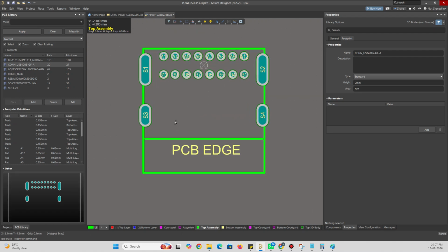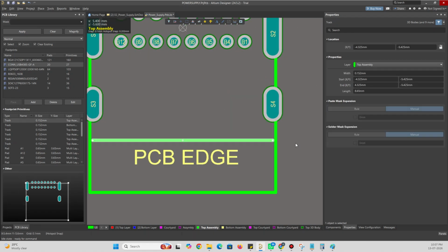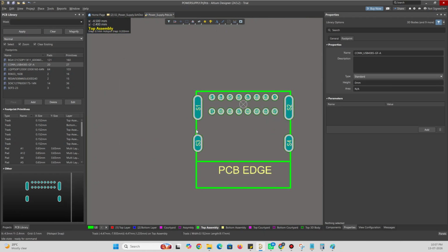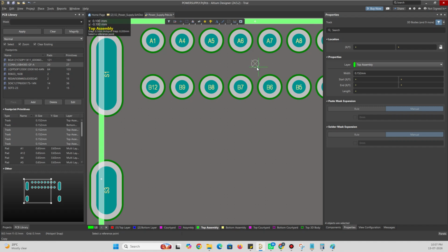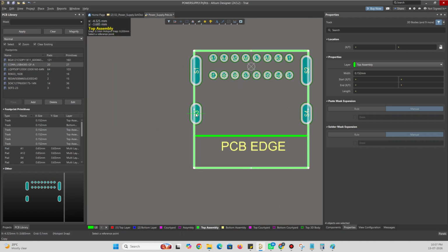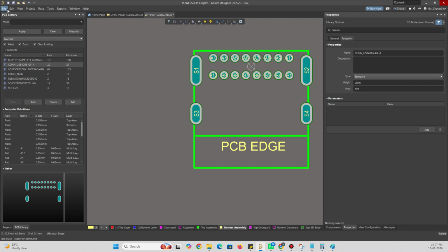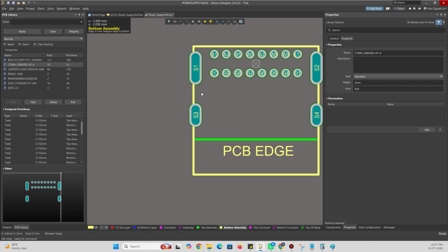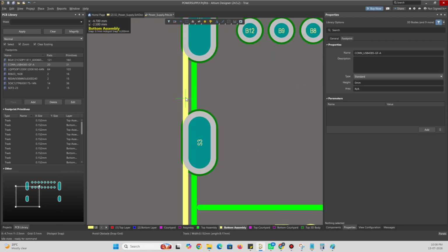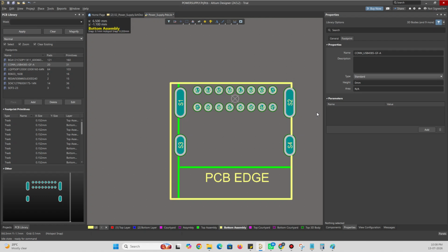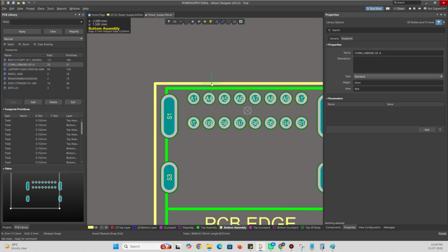So you can make it like this. We need to make the silk layer, right? Just copy all 4 lines, take a reference of any one point, in here or whatever it may be, and activate this layer, paste special. Paste it here and just move. You may set a grid of 0.1, drag somewhat here, this side and this side. If you want, you can move it up a bit.